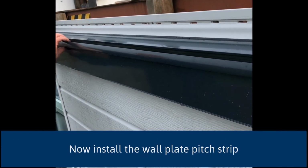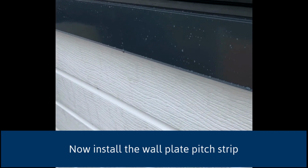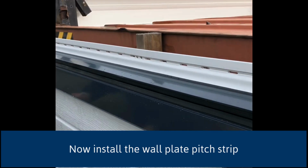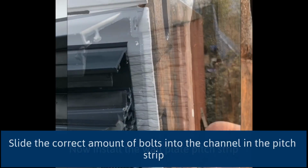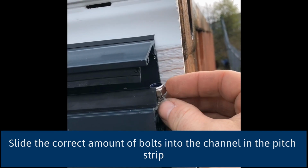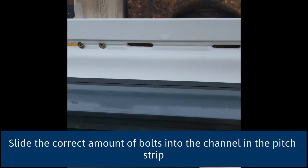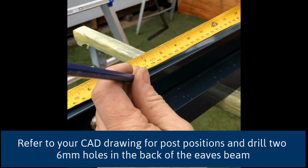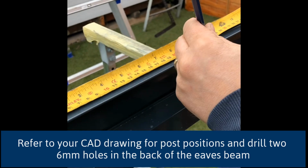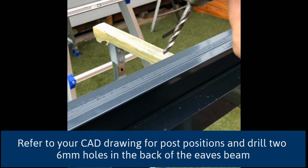Now install the wall plate pitch strip. This is the section that you will use to install the main bar plates. Now, mark your post positions as per the reference on your CAD drawings, and drill 2 6mm holes in the back of the eaves beam.